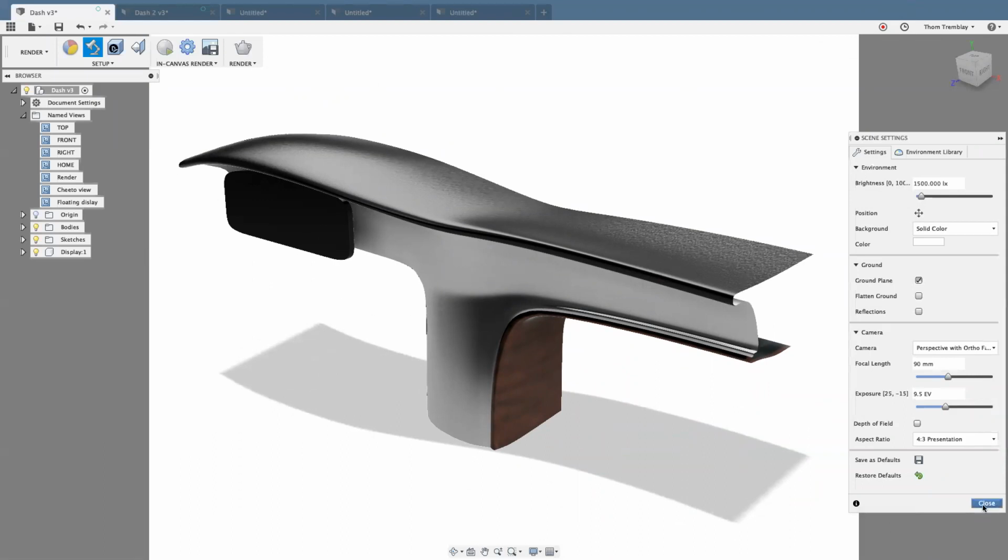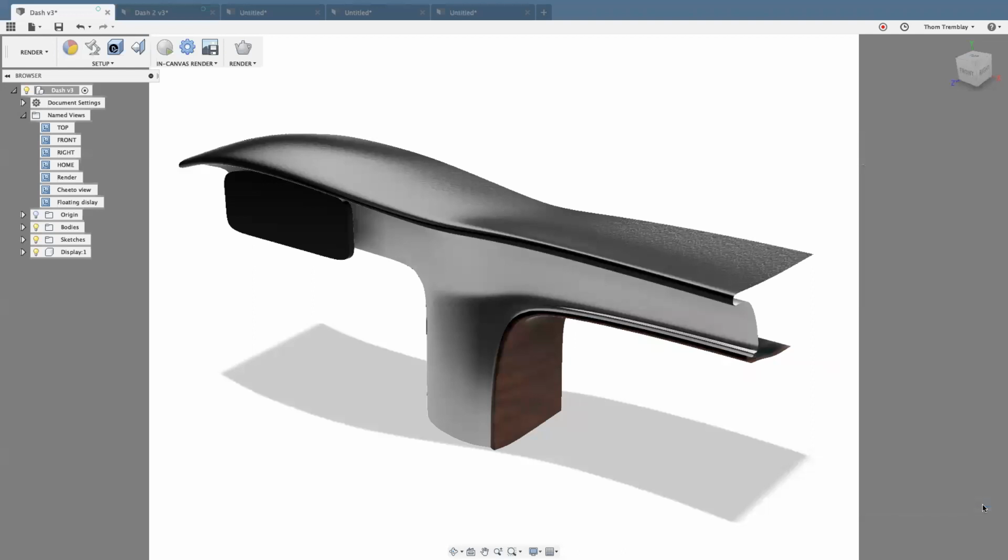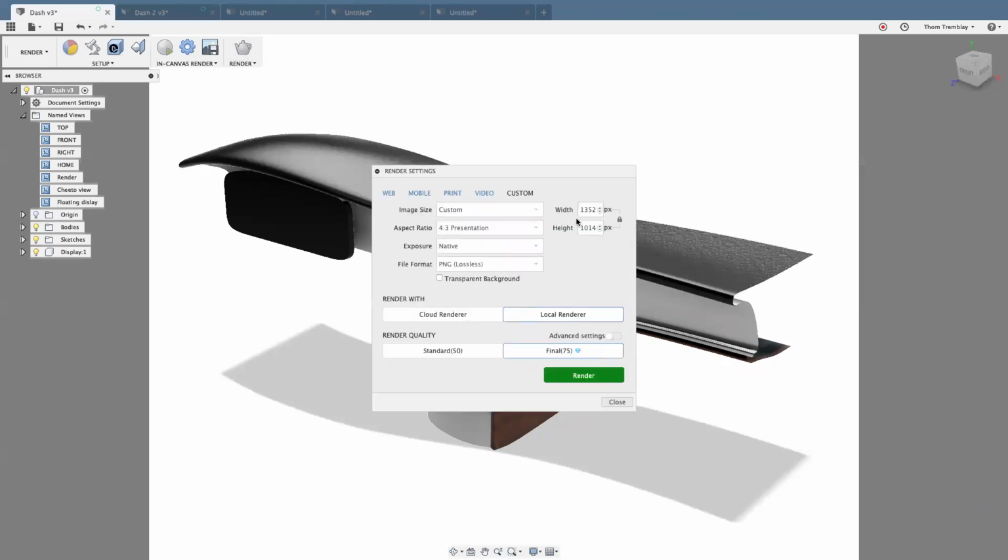Another thing related to that is, for example, when I create some of the content for Autodesk Education Team, they want thumbnail views or certain course images in a specific resolution. In my render tool, I can set up specific renderings. So I can say 1280, and I can unlink and say by 1024 and generate renderings to a specific resolution.